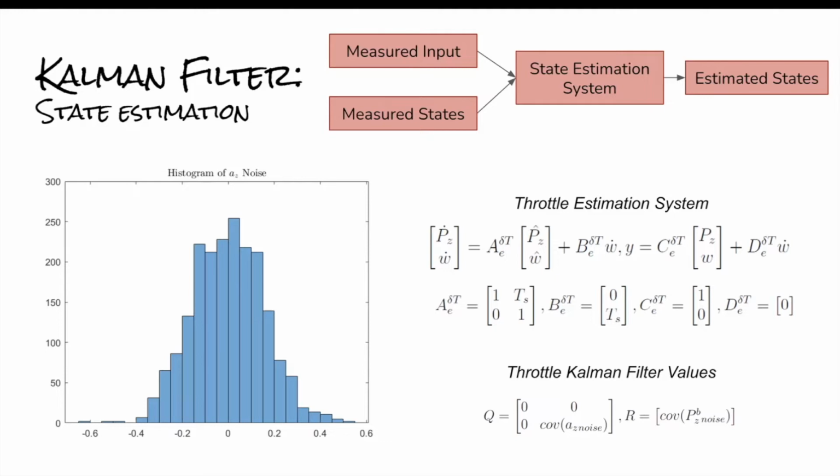And overall, this is how we got the inputs to our Kalman filter, and we worked to tune this filter by keeping our Q constant and then increasing or decreasing R. So for our aileron and for our throttle system, we weren't very trusting of this W measurement. So we decided to hold Q constant and increase R, which meant we trusted the W value less, therefore allowing our system to be more stable and work more like we expected and not be as affected by the noise that we had in the W measurement.